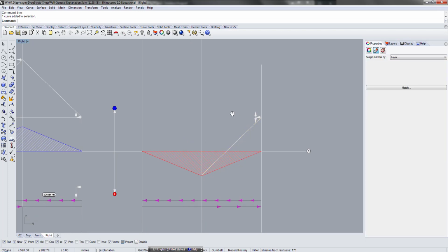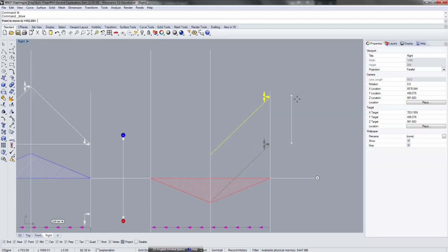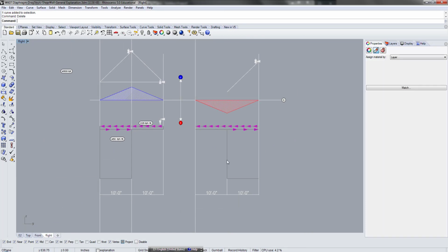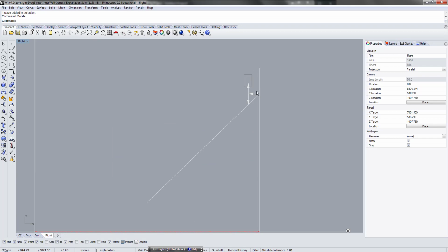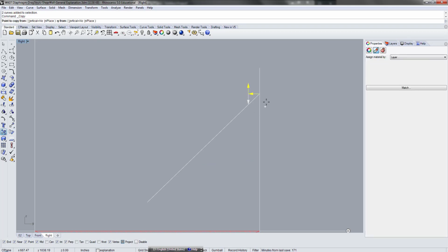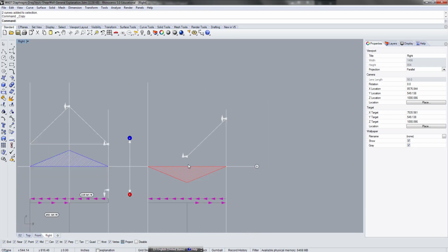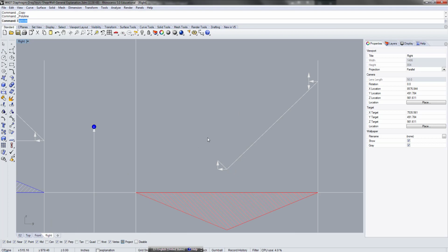That's why it starts out as a downward slope, and let me just move it up. But once you go past that wall, you only have this top shear, so that turns positive, because it's only that compressive force, and it becomes this upward slope.